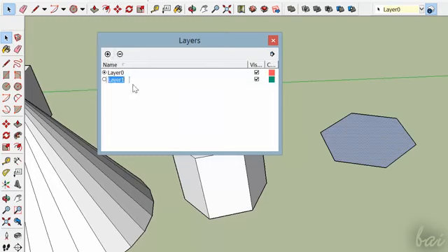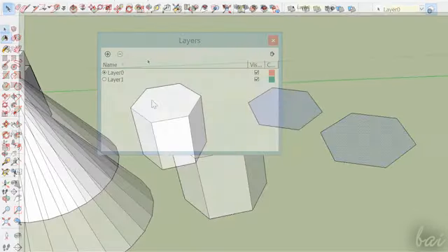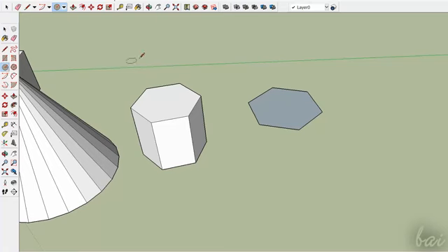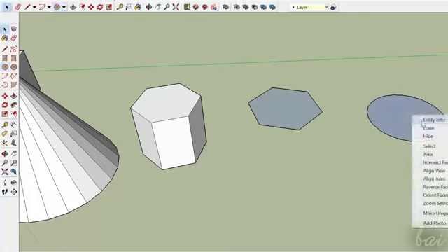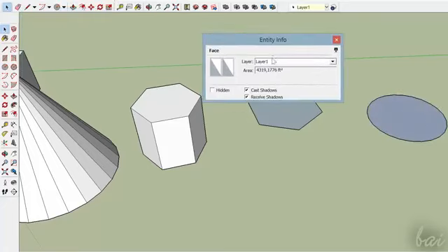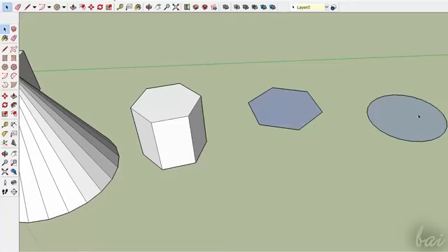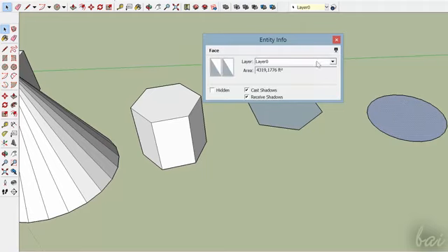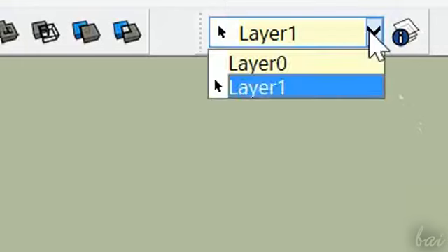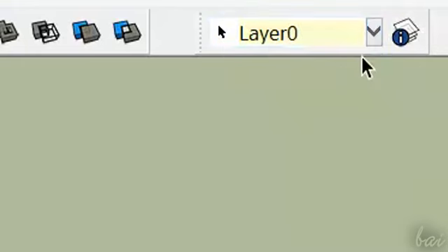You can create new layers clicking on the plus in the top left corner. The down arrow in the toolbar lets you choose the current layer to use. For example, if it is set at layer 1, all future objects drawn will belong to such layer. You can also change the layer which the object has to belong to by selecting the object and changing the layer using the toolbar. In this case, such toolbar is colored in yellow.